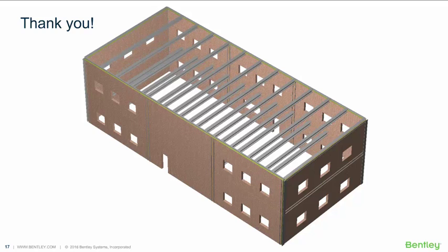All right. Good. I have a few here that I can address now. There's one about whether wall reinforcement represents both in-plane and out-of-plane. The answer is yes. RAM Elements designs masonry walls for in-plane and out-of-plane forces. So Josh mentioned that in the structural system you cannot apply an out-of-plane load, but once you're in Elements, you can apply a pressure to any of your walls and have the module design it also for those out-of-plane forces.